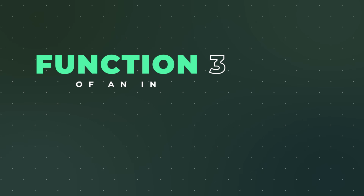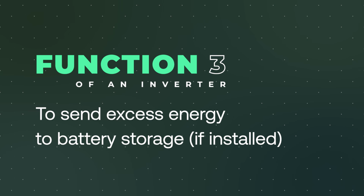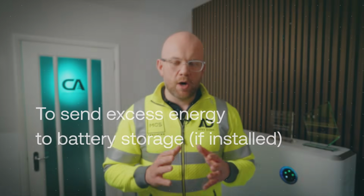The third main function is storing it inside of battery storage. Now, I'm going to deep dive a tiny little bit on battery storage later on in this video itself, but effectively, your inverter can convert the DC, step that voltage down into a lower voltage DC often, store it, and then when we turn our kettle on, the power can be converted via the inverter from DC to the usable current of AC.